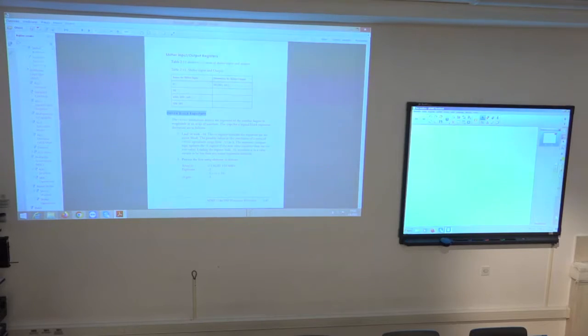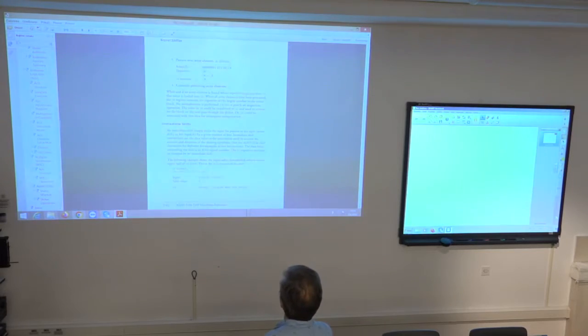And this particular operation is useful in the implementation of the fast Fourier transform. When you implement a fast Fourier transform, it is useful to always keep the data normalized, to have the data values at the leftmost position in the register. This way you avoid the round-off error of the computations. So that is the reason why this block exponent detection is a useful instruction.